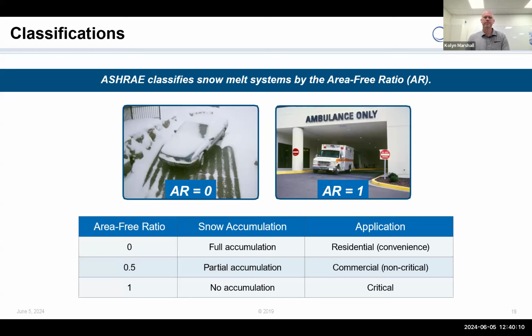If I say, I'm 95% accurate on my 12 inches, that means there is some variable that says I'm going to get a 6-inch snowfall and a little bit that's going to get an 18-inch snowfall. But overall, I'm going to have about a 12-inch average. But there's a variability on individual snowfall events. That will factor in a smaller or a lower overall BTU load because I'm accepting the fact that on the lower snowfall side, the system's going to respond faster. And on the higher snowfall side, the system's going to respond a little bit slower.